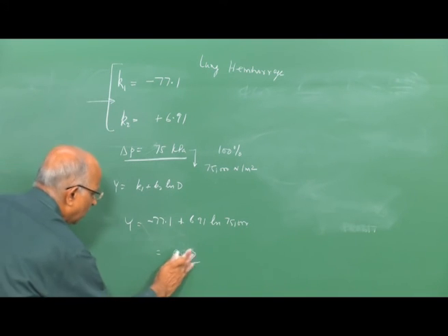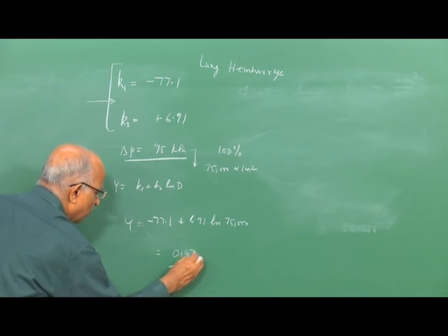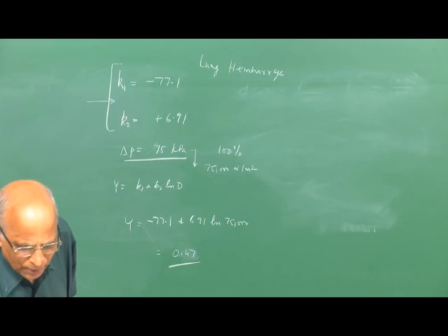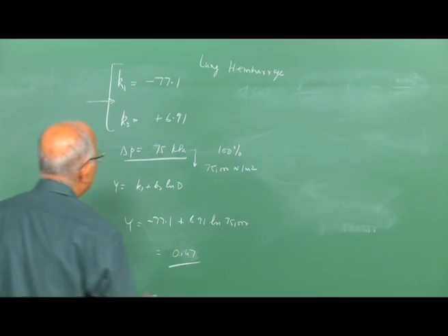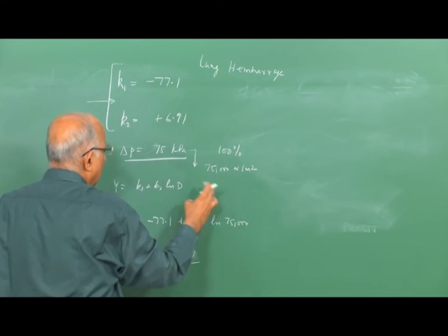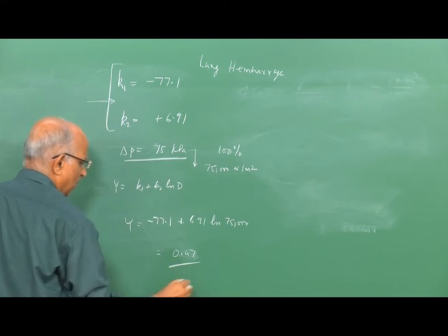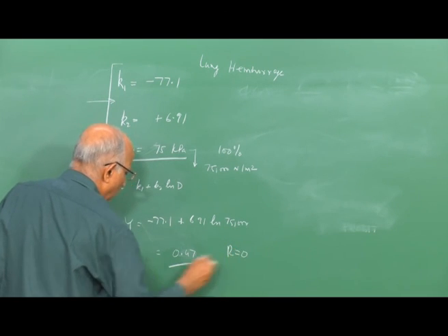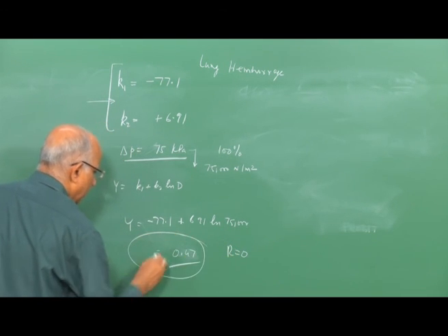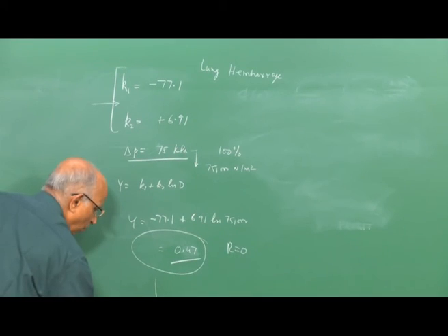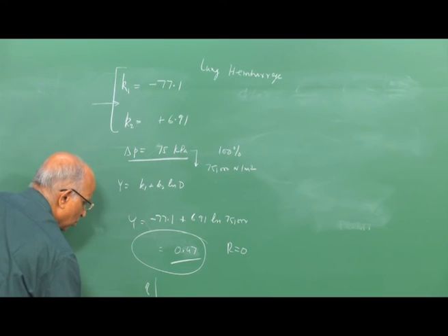If I take a look at 0.47 in my particular figure, well, it is almost 0. That means none of the people's lungs are getting affected, even though all the glass windows get ruptured and all that, people are still safe. The response is 0 because my value of probit is so small that the response for this particular probit Y is 0.